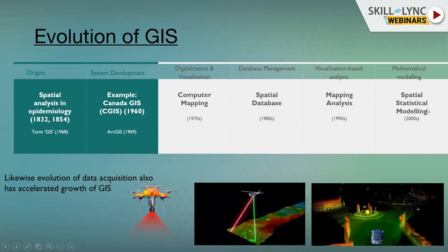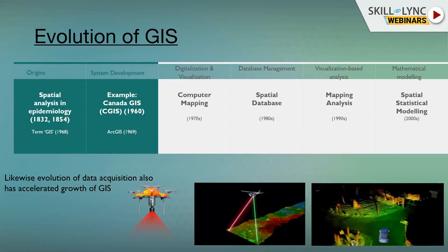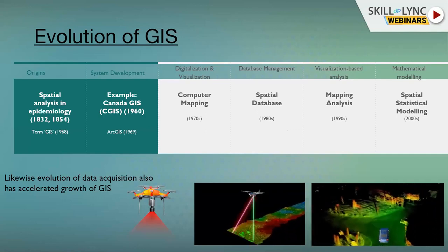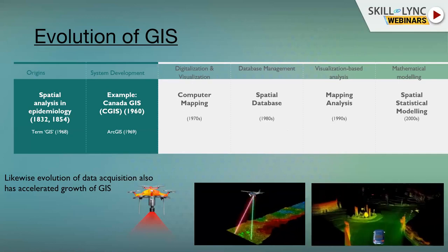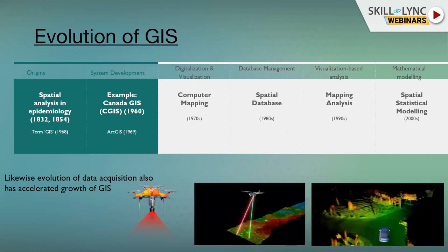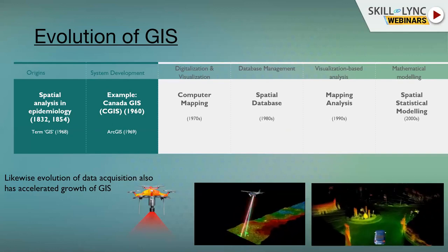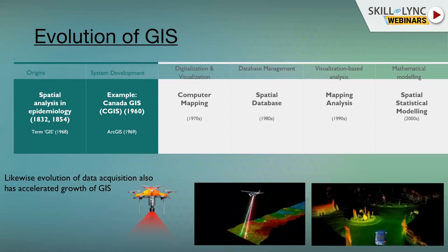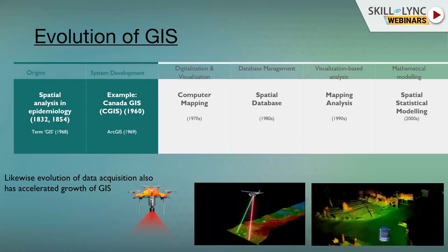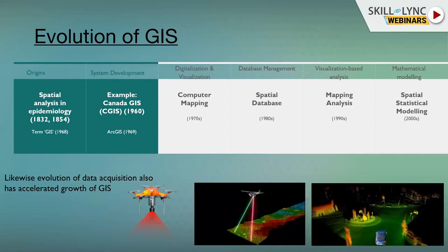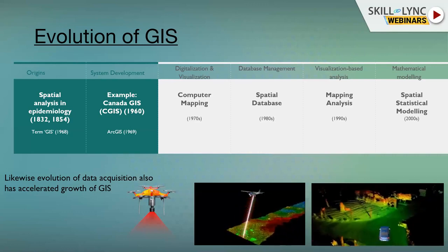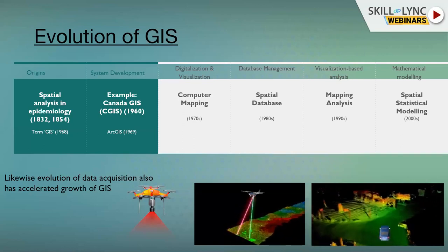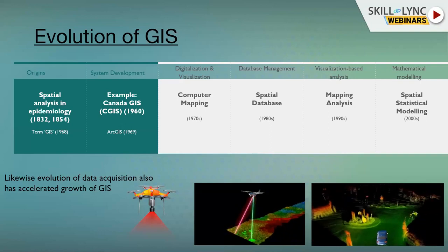I'll tell you a beautiful example. Suppose you are constructing a port, you need to see what changes happen to the coastline if you are constructing a barrier somewhere, right? It will let you know. There are very good mathematical models which let you know the shoreline change, how much the siltation will be, where you need to build your groins so that there is no siltation there, and on which extent of the shore there will be more siltation. So that's just a simple example.